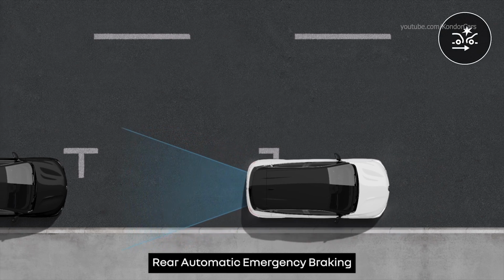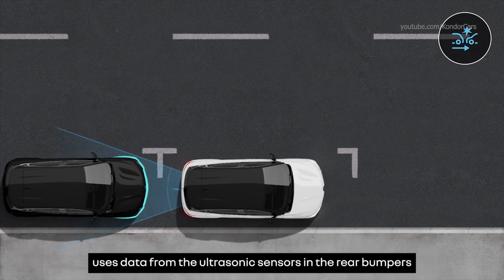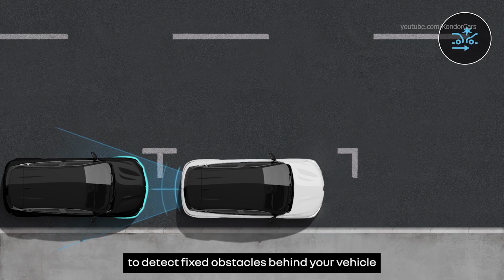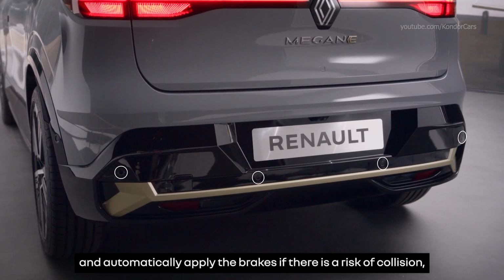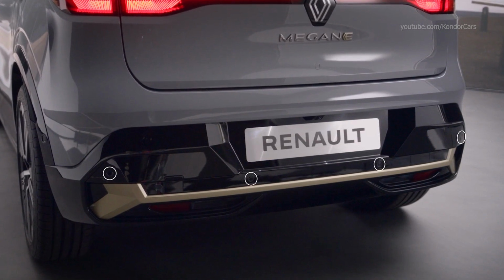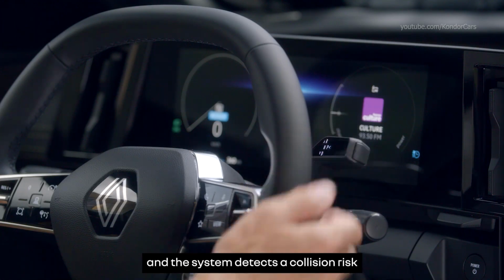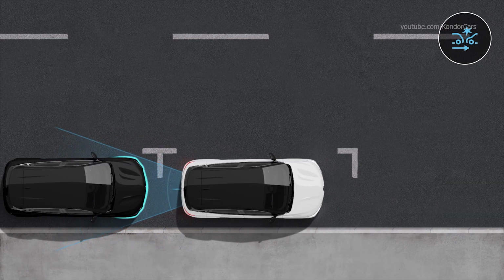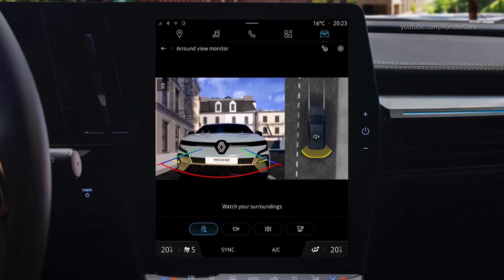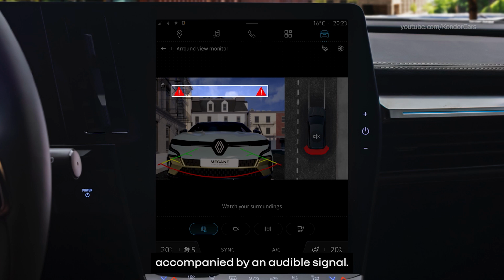Rear automatic emergency braking uses data from the ultrasonic sensors in the rear bumpers to detect fixed obstacles behind your vehicle and automatically apply the brakes if there is a risk of collision. If reverse gear is engaged and the system detects a collision risk with a fixed obstacle, it automatically applies the brakes. This symbol is then displayed on the multimedia screen accompanied by an audible signal.